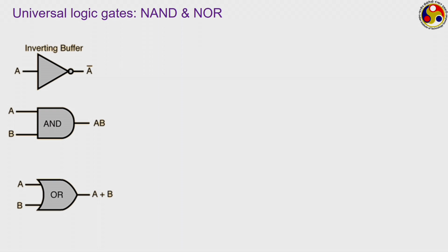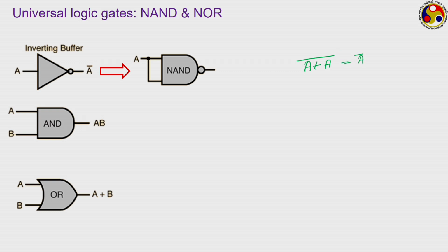How do we get the NOT operation using a NAND? NAND is AND and NOT. So, here both inputs will be coming from the same source, and then it will just act like a NOT operation, because you are supplying A as both inputs. So, you are going to get A and A with a NAND over bar. So, what is going to be the result of this? It has to be A bar only.